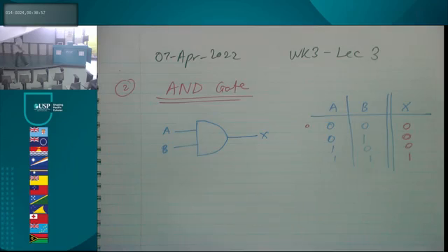In order for the air conditioning system to turn on, you need both sensors to trigger, saying yes, we have reached the temperature. Let's say 26 degrees Celsius: the moment you hit above 26, both sensor A and sensor B will trigger and tell the air conditioning system to turn on.